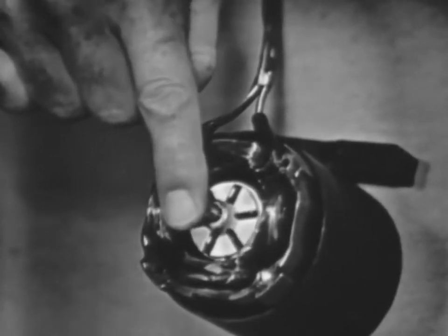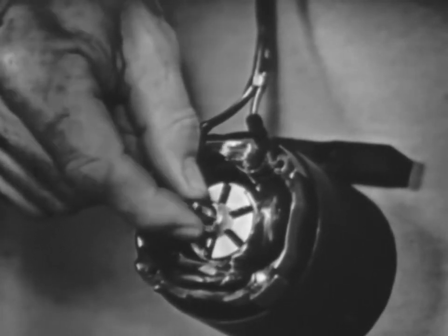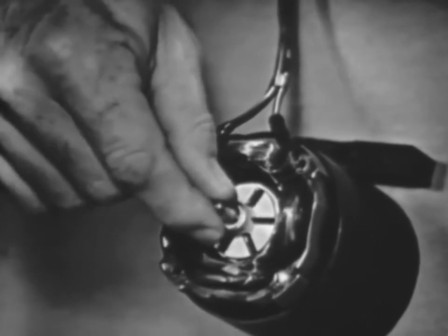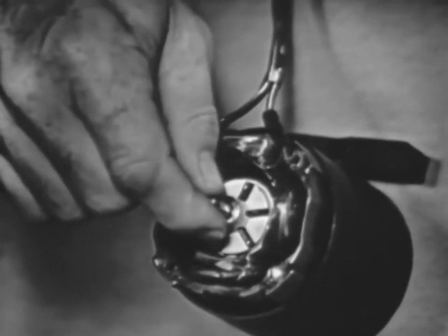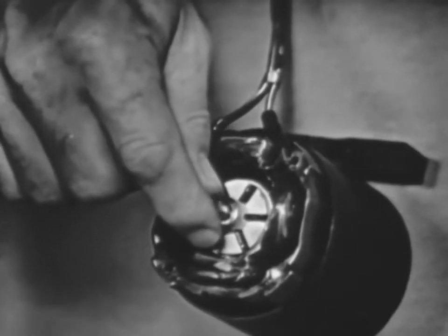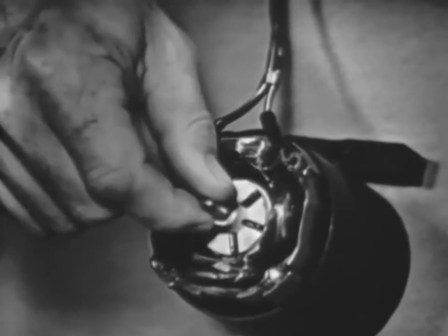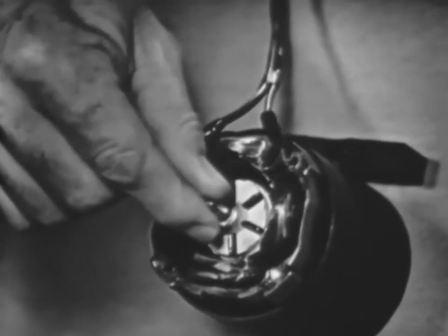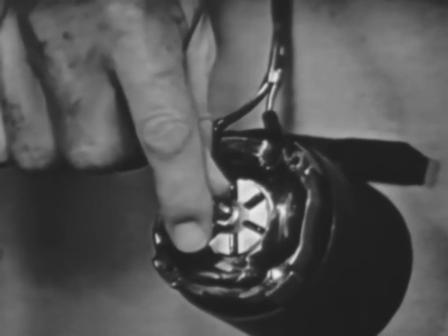Now, there's a limit to this. I thought there would be. For example, if I make the load on the motor too great, as I'm doing here with my fingers, it stops. But the magnetic field is still zipping around there, right? Right. Nothing slowed it down. So the frequency of cutting has gone way up. Now, from this, you might think that the current in the rotor, when I've got it stopped like this, has also gone way up. But that's not so.